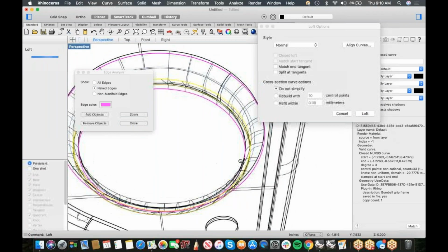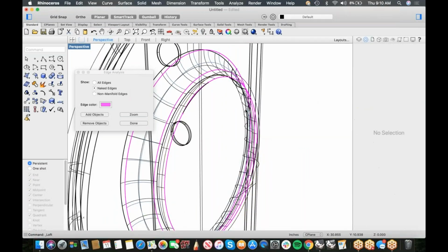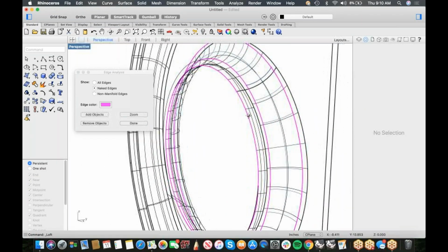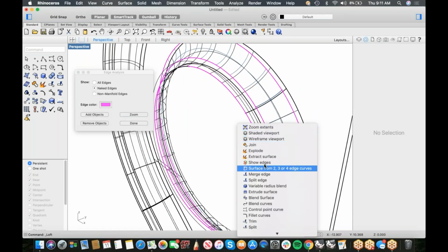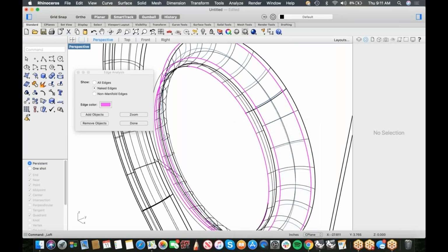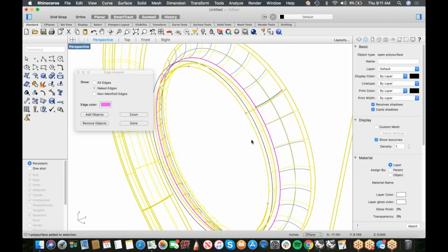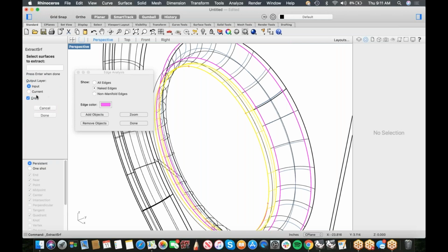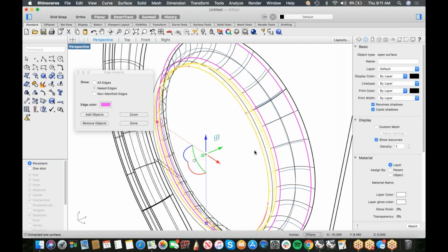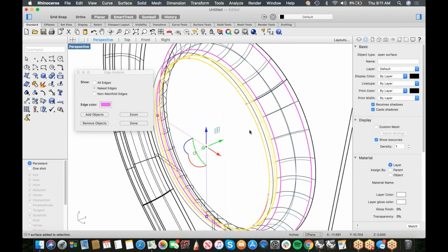Let's see how that looks. I'm not in love with that as a surface, so let's cancel that. Let's build this surface first. So let's loft from here. I want to get clean surfaces. So, and it looks like this object, let's extract this one. I don't want to copy it. That little green arrow that popped up indicated that it was copying.